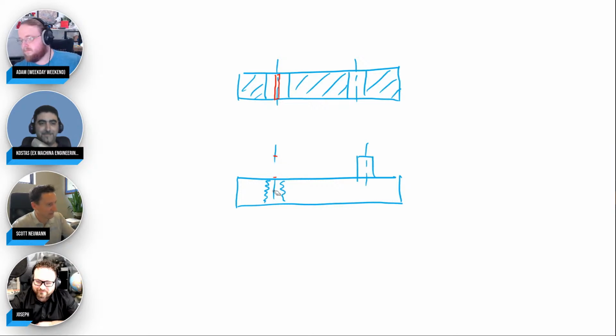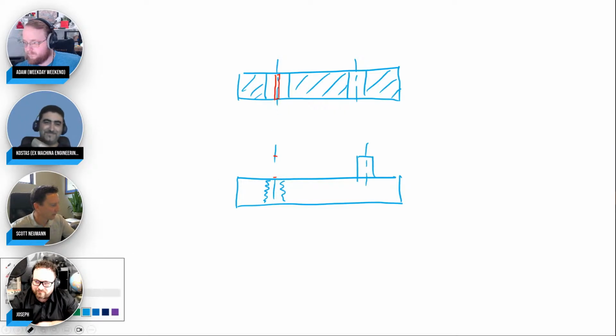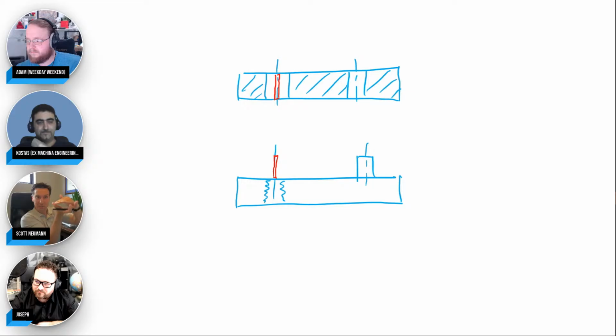When I'm positioning, the hole doesn't mate with the hole. It's the bolt that goes into the hole. So you don't want the tolerance zone to be the length of the feature like it normally is. You want the tolerance zone to be projected out where the bolt is going to be. That way, when I put these two parts and mate them in the CAD, the tolerance zone will overlap with the tolerance zone, and you're back to a really easy smallest hole, biggest pin calculation.